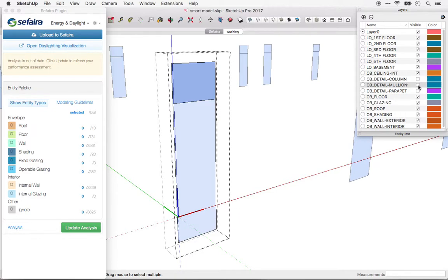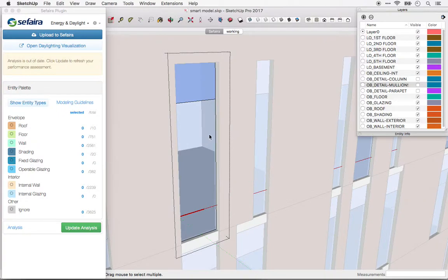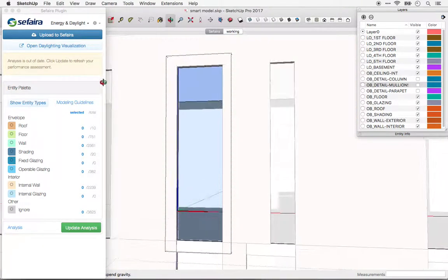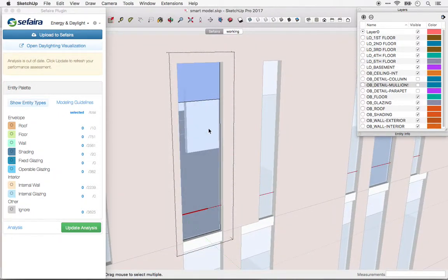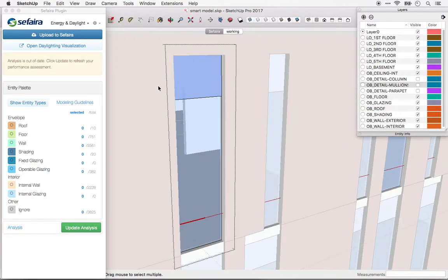What you'll notice is that the glazing is the full extent of the window. It goes all the way edge to edge. If I unhide the rest of the model, you can see it fully fills in that rough opening of the window. And that allows me to have a full envelope and not to have extra penetrations for things like daylight analysis.